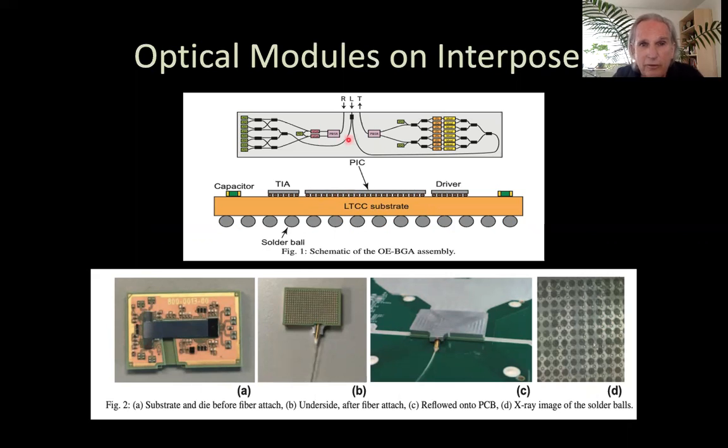And the silicon photonics here, we see all kinds of devices on here, modulators, and we see that we've got couplers for demultiplexing and multiplexing on top of this device. And this is what these look like. These are actual physical layouts of what they look like, where we're talking about, again, an interposer package. We talk about interposer packages, and oftentimes these interposer packages have ball grid arrays hooking them to some kind of board.